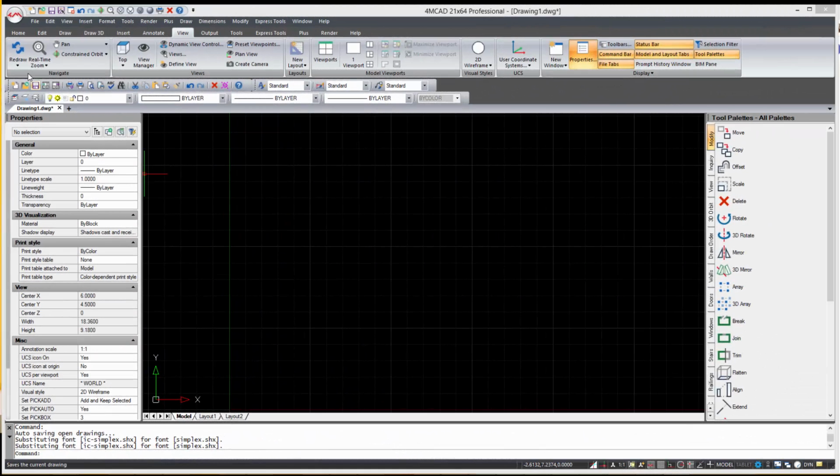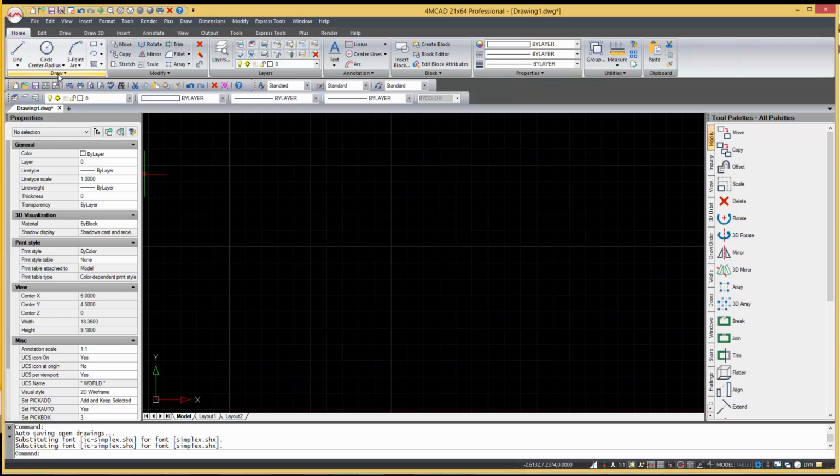Now, let's see how to design 2D entities with CAD. You can design lines, circles, ellipses and polygons with the commands in the Draw panel, that you will find under the Home tab. You can hover over each tool to get tips on how to use each command and on the kind of tool you choose from the list, if there are more than one option for some commands.